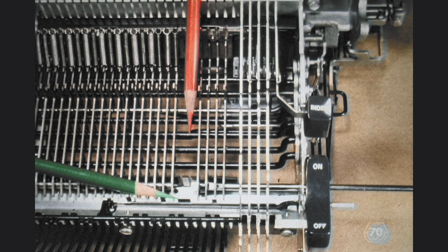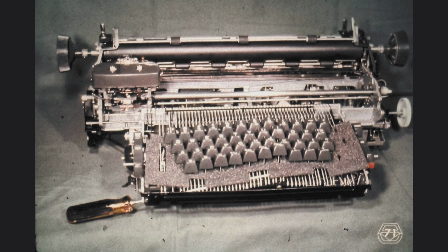Now let us reinstall the interposers and then fold down the keyboard. The keylevers are easily reinstalled by using a long screwdriver to lower the keylever restoring springs, as shown here. Once the keylever restoring springs are held out of the way, we only need to align the keylevers with their respective slots, and then reinsert the rubber-covered keylever upstop. When you're finished with this reassembly of the whole keyboard, we shall start with the keyboard adjustments. Take the time now to complete the reassembly of the keyboard.